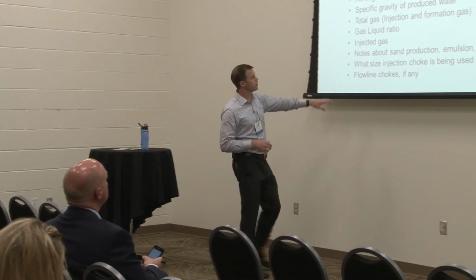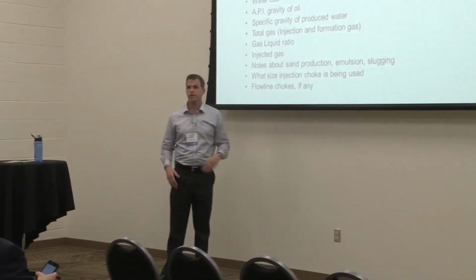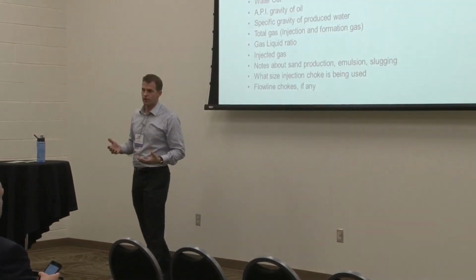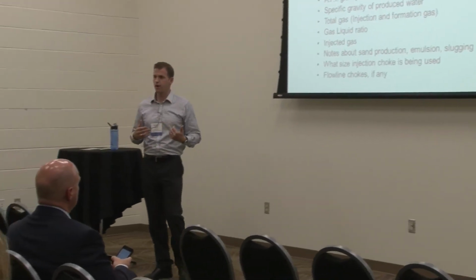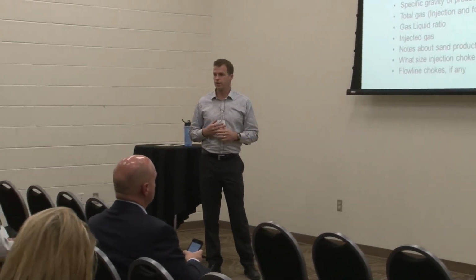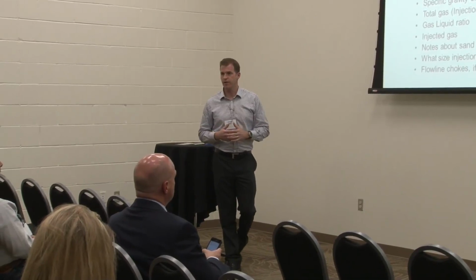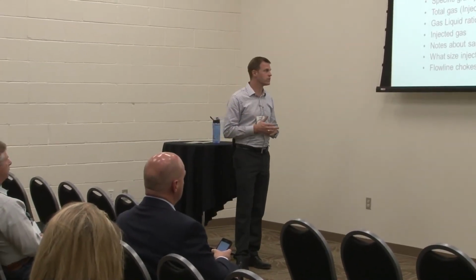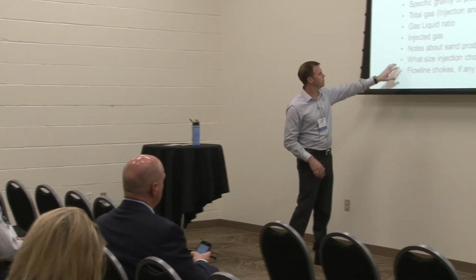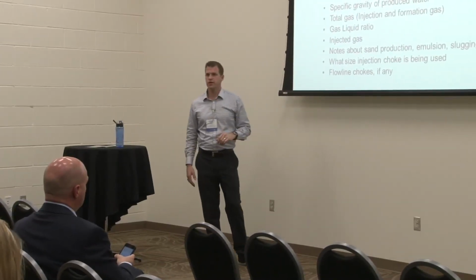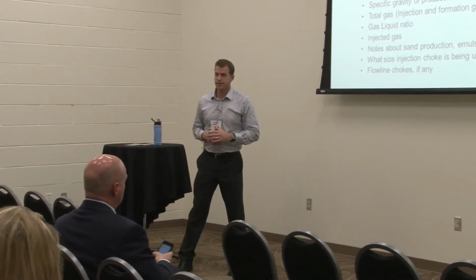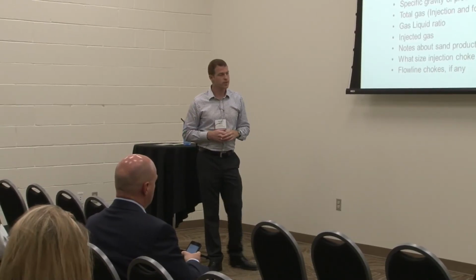It might be undersized for injection chokes. They might be oversized. They might be utilizing something that they could take from one well site and bring to another to lower costs and help prevent adding inventory to their wells. So really making notes of equipment inventory on location goes a long way with the well test and full field optimization.